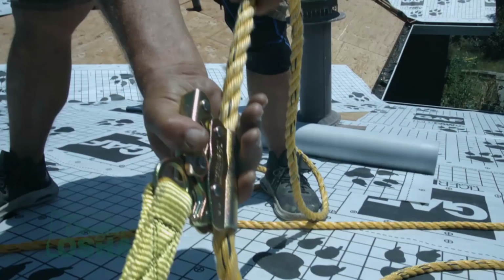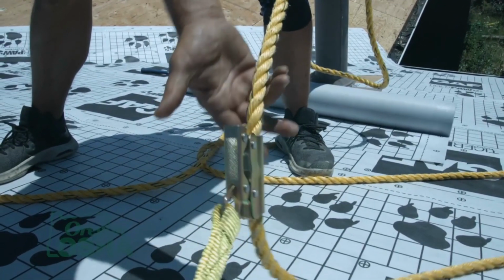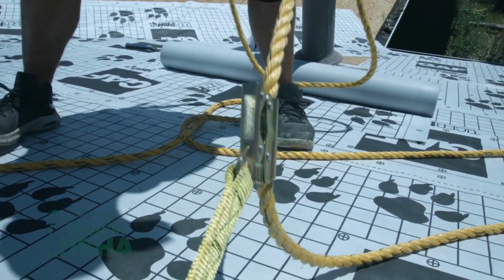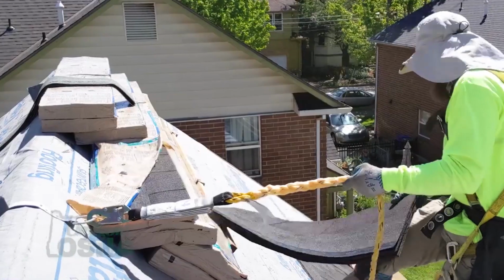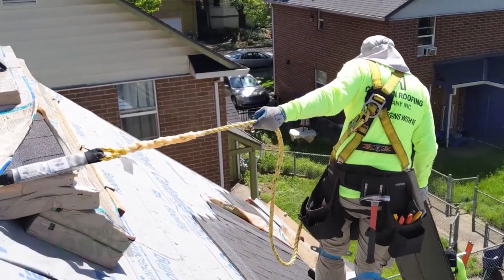The most critical thing that you have to really train employees on how to use are the rope adjusters, to make sure that they are constantly adjusting them to where the area that they're working, so that they can get to the edge of the roof but not go off, but so that when they get up on the roof, they think they need to adjust the rope length so that they're not falling further than they need to. So if you're working on a 10-12 pitch especially, and if you slip, you don't want to fall all the way to the bottom of the roof before your rope really stops. But that's the most critical thing, is making sure that employees are adjusting their ropes and keeping them at the proper length.